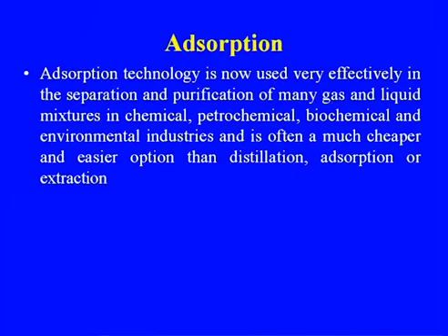Another development in the case of the separation process is adsorption, that is, the physical adsorption technology, which is now used very effectively. Earlier, carbon adsorption was one of the very common processes, using activated carbon for the purification of water. From ancient times, charcoal was used for cleaning, even for the purification of water.